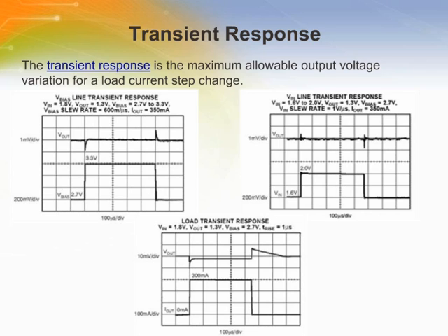As with any regulator, increasing the size of the output capacitor reduces over- and undershoot magnitude, but increases the duration of the transient response. The transient response is a function of the output capacitor value, the equivalent series resistance of the output capacitor, the bypass capacitor, and the maximum load current. The application determines how low this value should be. To decrease voltage variation resulting from a load transient, a big value of output capacitor and a low ESR of the capacitor are recommended.